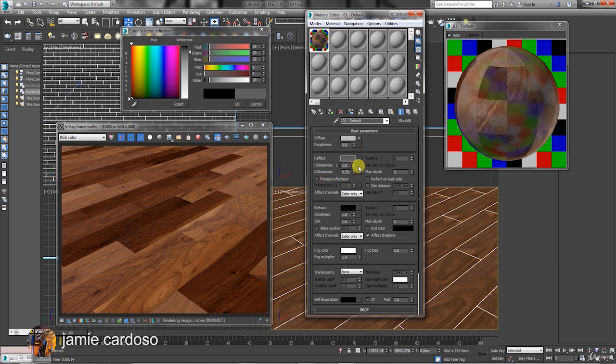To diffuse the reflections, simply reduce the reflection glossiness values slightly. To add specular highlights on a surface, simply reduce the highlight glossiness value slightly. The smaller the values, the more diffuse the highlights will be. You can control the amount of reflectivity by tweaking with the color swatch. Darker colors reduce the reflections and brighter colors do the opposite.